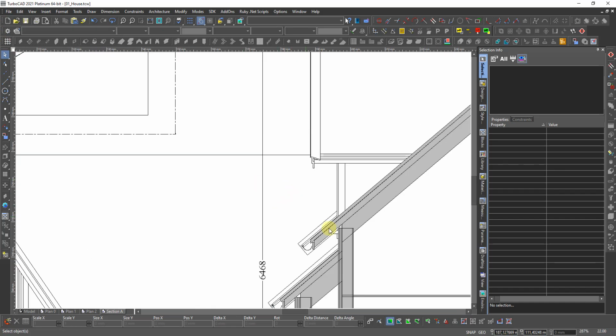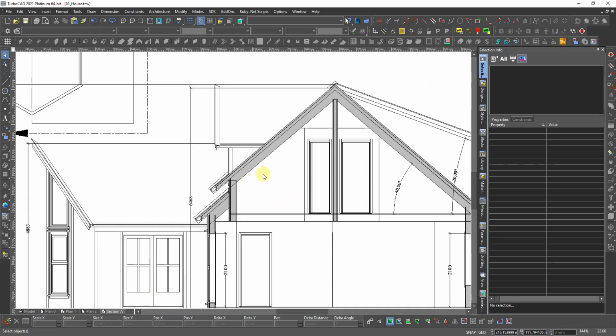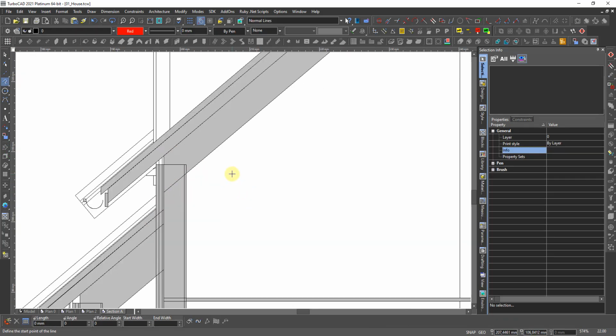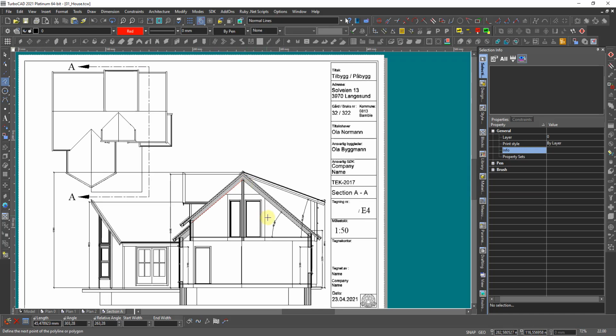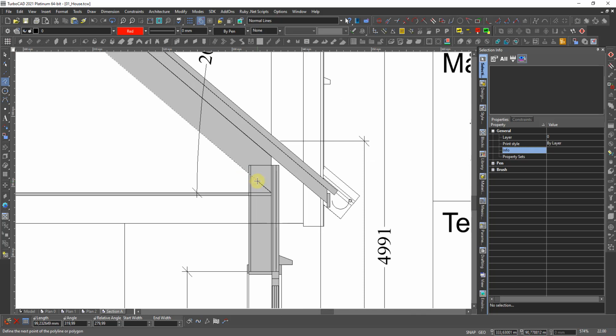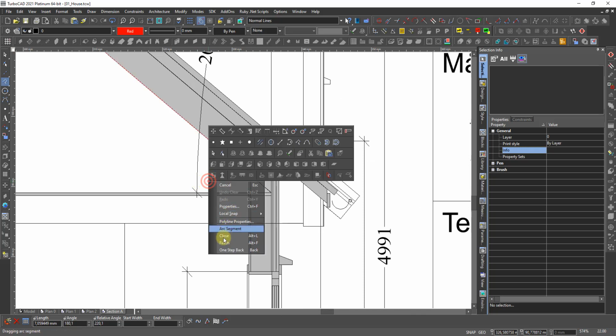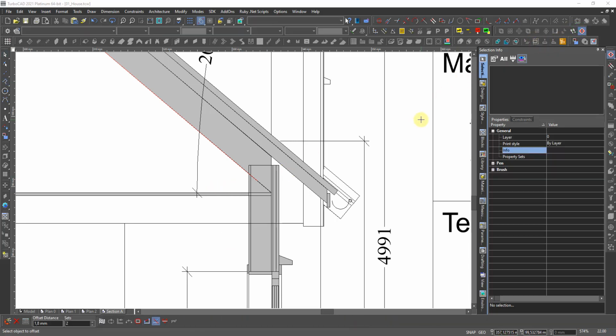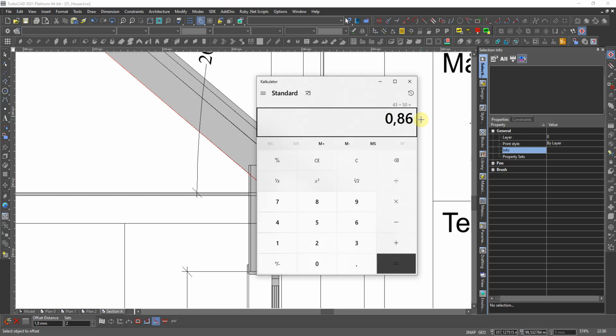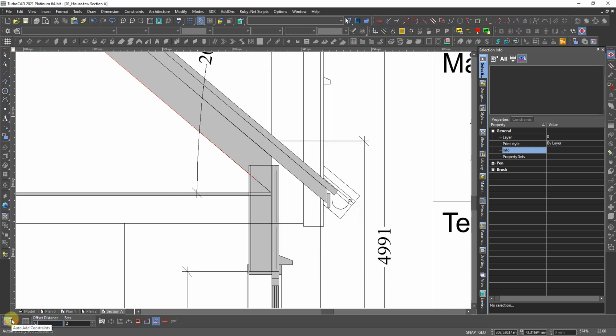Now before that, I see you also want to know this height. So I can draw a polyline. From nearest and up here to the V, and then down again to nearest, and I say finish. I offset again, and I count this, and I have 43 divide on 50 is 0.86. 0.86.